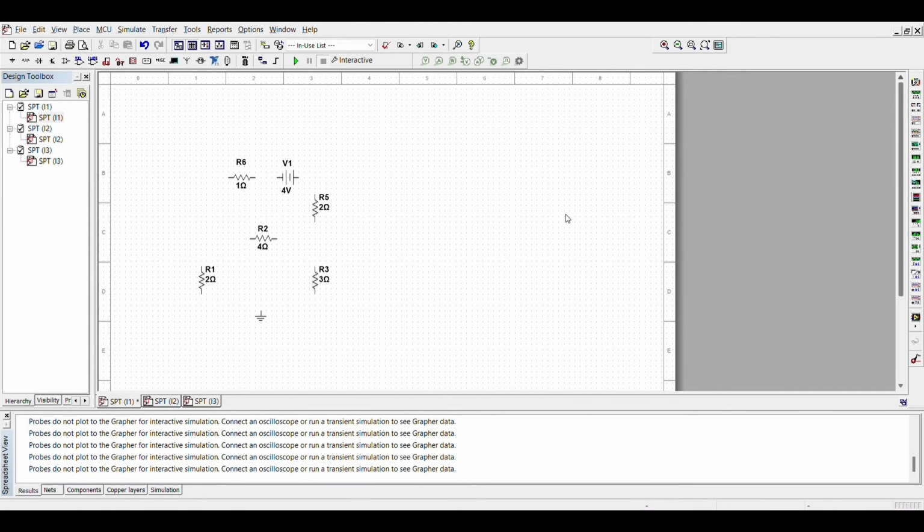For this circuit, we are going to find the value of current. So as you can see, for this circuit, we are going to turn on the V1. So I1 and I2 will be open circuit. So the first thing is we need to connect all the component together. After we finish connect all the component, we have to take the probe current and put it at the place that we want to find the current. So we are going to find the current for loop 2 and loop 4. So we put it here and here.